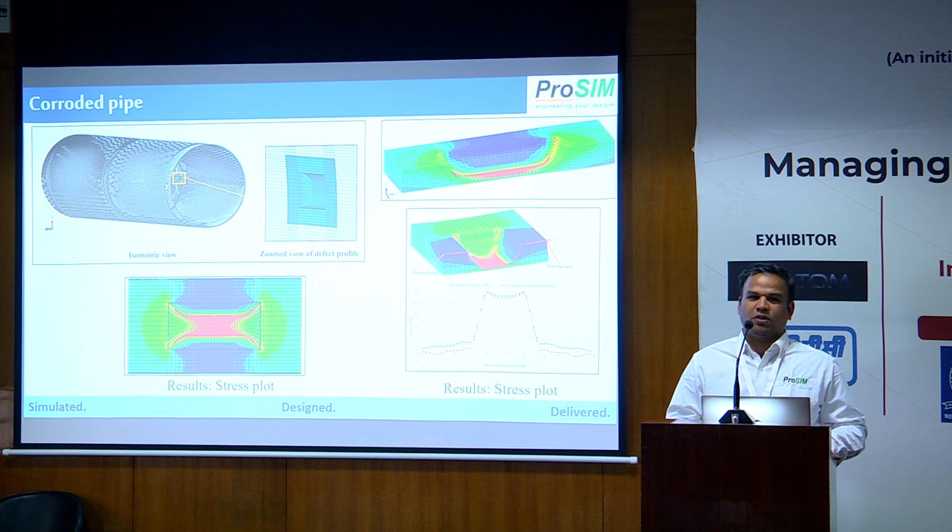We have checked some of the circumferential welds where SCC has been found and cracking has taken place. That is because of the combination of material degradation, a corrosive environment, and the strain rate of the defect.